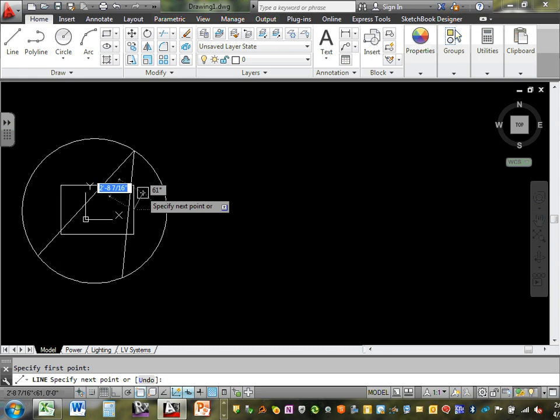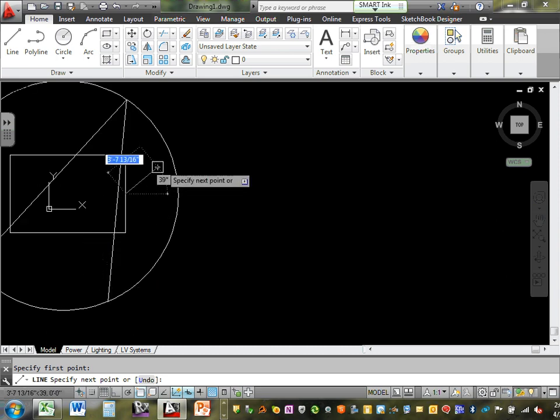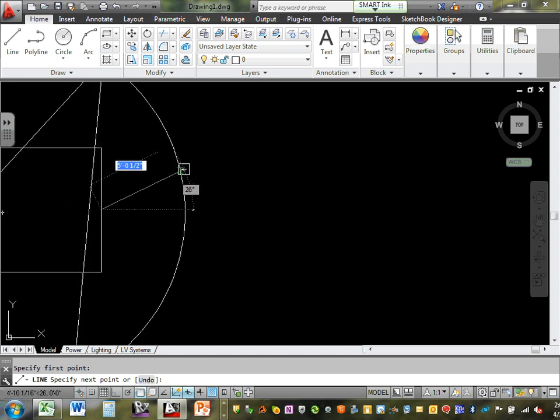Where else do we want to take it? Okay, let's take it to the closest point, just tie it to the circle, anywhere. Okay, so click on the circle. Now I snapped it from the center to the circle. Okay, and when you click, hit escape. When you click, hit escape. So you snapped the line from the center of this line into somewhere on the circle.